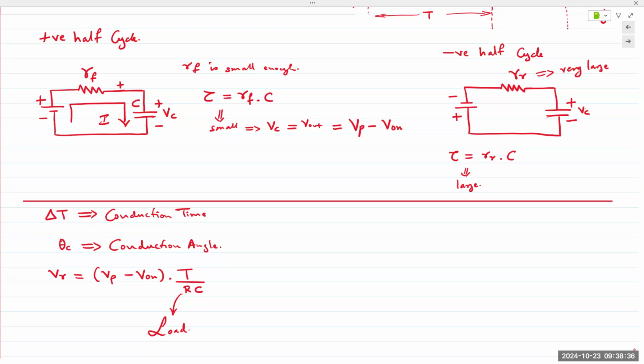Now everything is standard spec USB. And so USB spec is standard 5 volts. You can change the current. The minimum spec for 5 volts is 500 milliamps based on all the computers that we have. Chargers now come with varying voltages and with varying currents, but you can still obtain the standard spec from the output, from your chargers. Okay, so those power supplies are designed to work with a wide variety of loads.